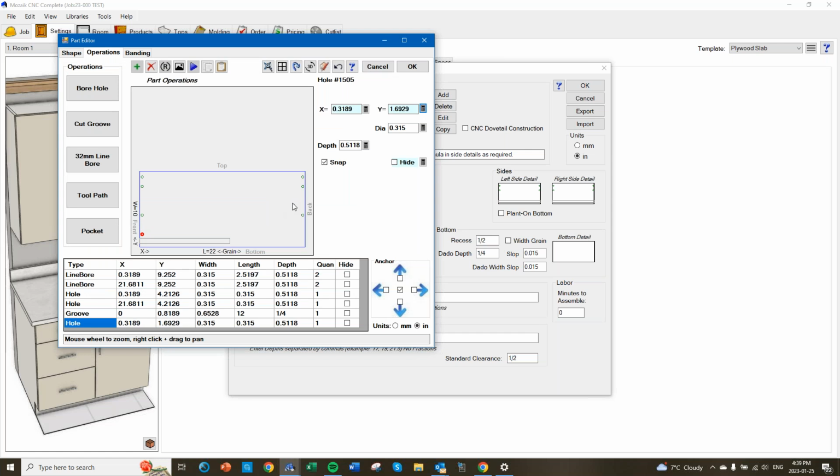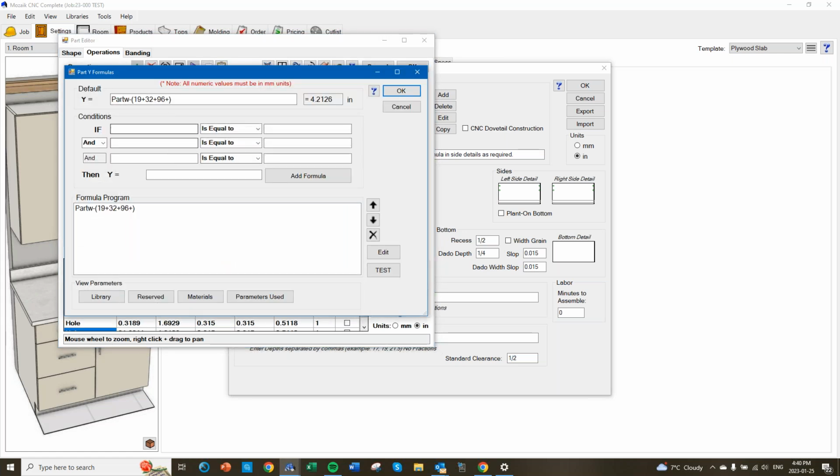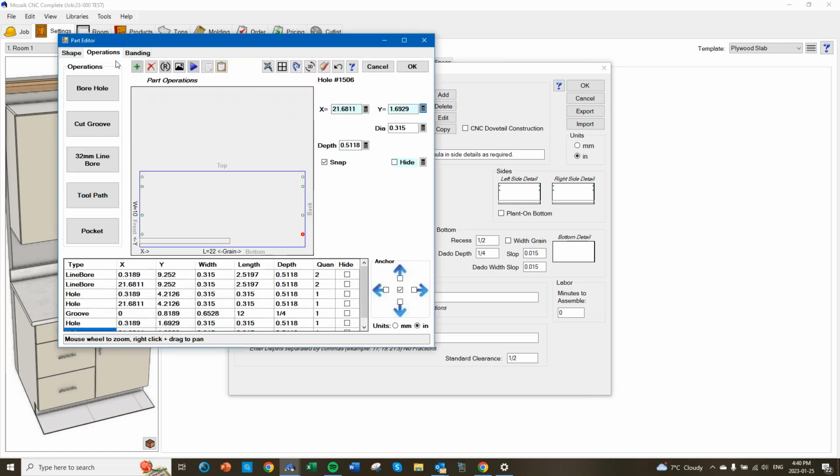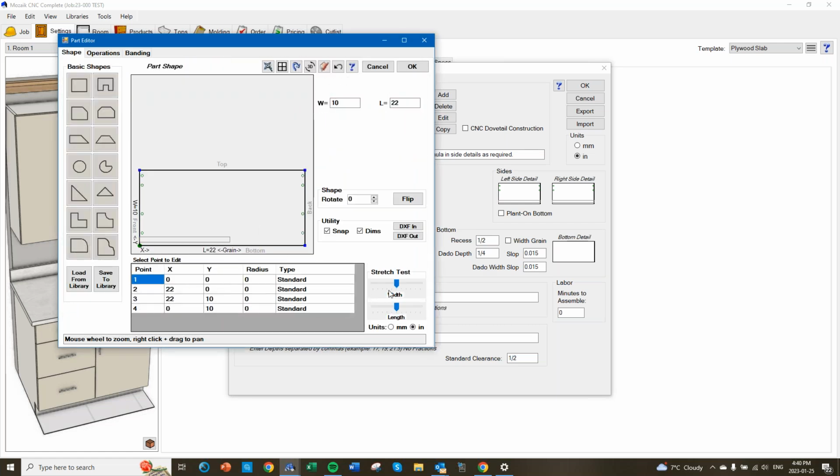And the back too. Then we'll take this guy, copy that, and paste it, change the Y formula to that, and click OK. So now if this guy got narrower, see how they drop off? And if it got wider, at least you have the 4 of them in there. So if that was like a 12-inch drawer, that's fine. If it dropped down to like an 8-inch, then it drops off.